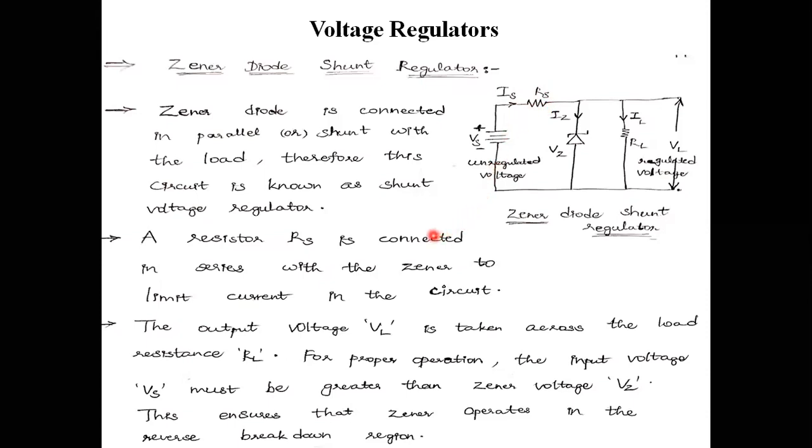Sudden flow of current into the circuit will lead to damage to the entire circuit. So I'm going to place one resistor here. That resistor, I can treat as a current limiting resistor, that is Rs. Across the Zener diode some flow of current is taking place. That current is Iz. And the voltage across this Zener diode, I can treat as Vz.